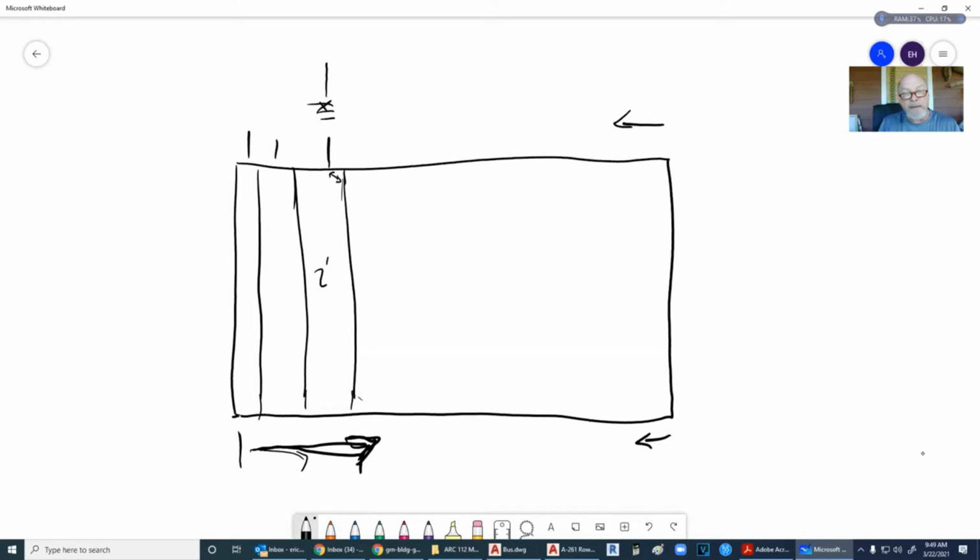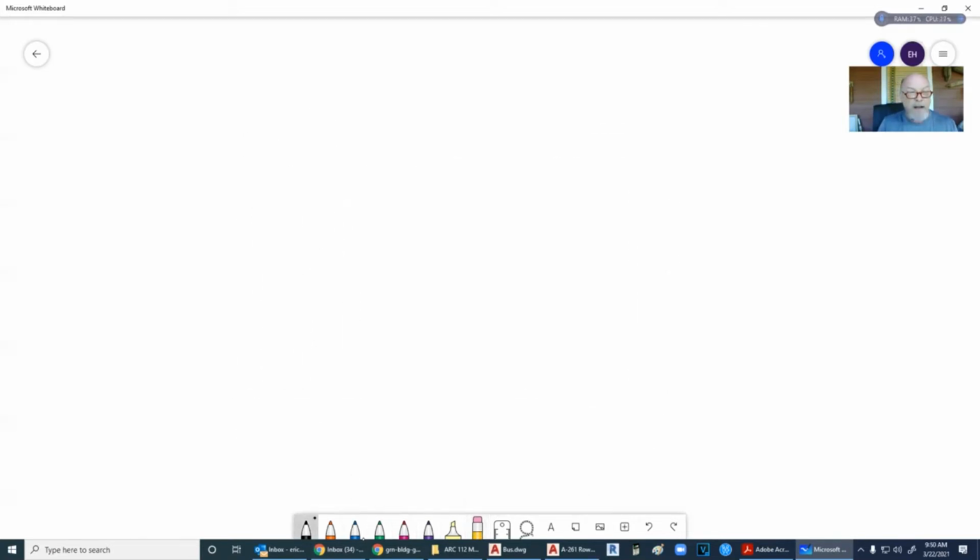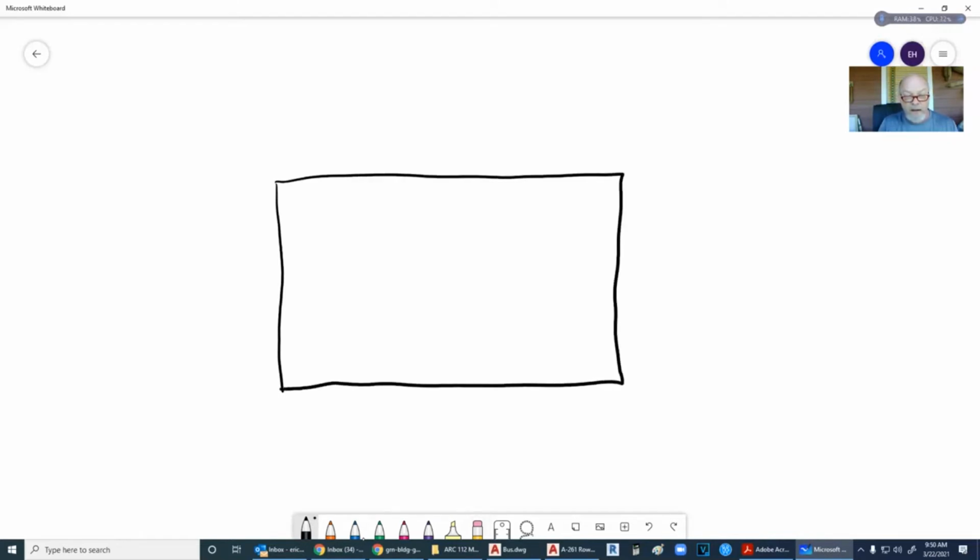He made us put up a double top plate, even though we went back with the trusses perfect, but he wouldn't go with it because it missed that criteria at the floor joist. I know that kind of sounds silly, but when I say ground rules, this was something that I always made sure all my guys knew about.